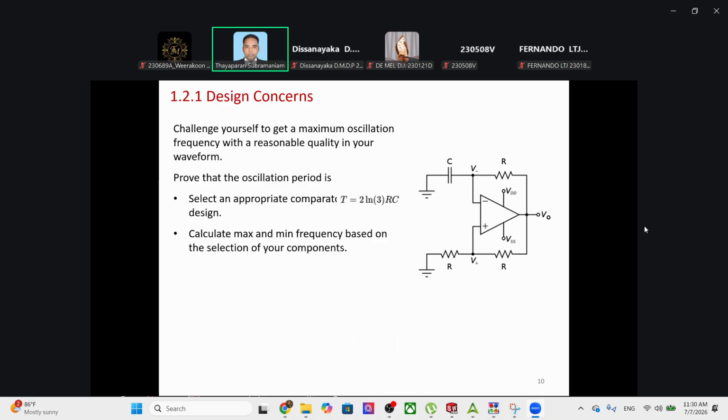It is 2 nanoamp, I mean, it is not the typical value. Please note that you have to consider the maximum value. The maximum value has to be less than 1%. Suppose the maximum is not available, you can consider the typical and add some safety margin. Say if the typical is 2 nano, you can consider 5 nano as the maximum by yourself. You have to write that assumption. I consider 5 nanoamp as the maximum, and therefore 5 times 100, 500 nanoamp, 0.5 microamp.